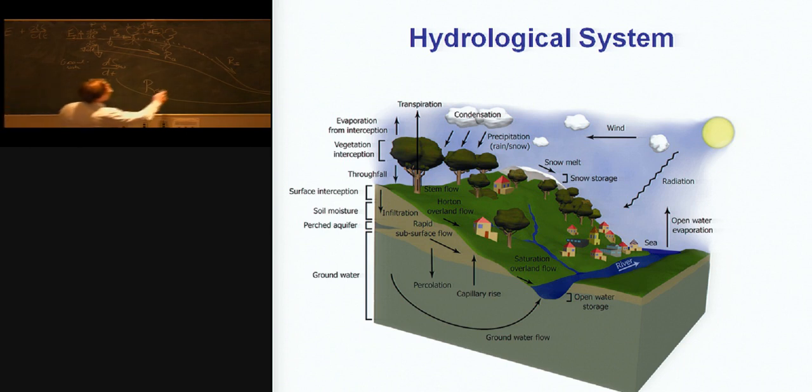We have the surface runoff, the RS, the unsaturated zone subsurface runoff, RU we call that, and we have the groundwater runoff, RGW. Yeah, these are three different runoff components. Yeah? And then it all goes through that river, flowing into the river, and that's then the final runoff. I just make a big R.